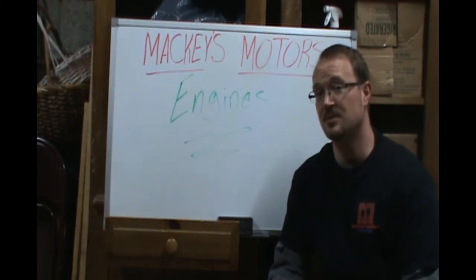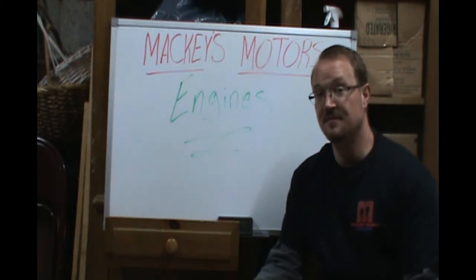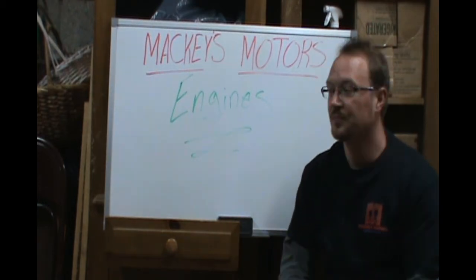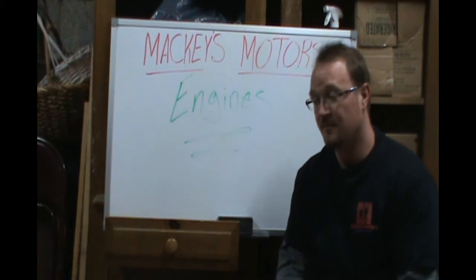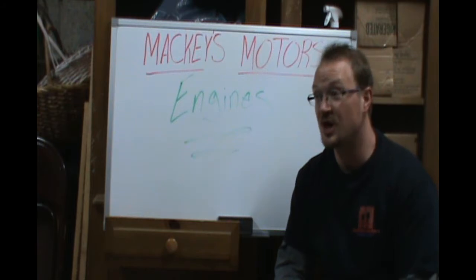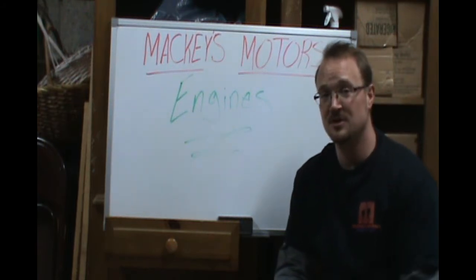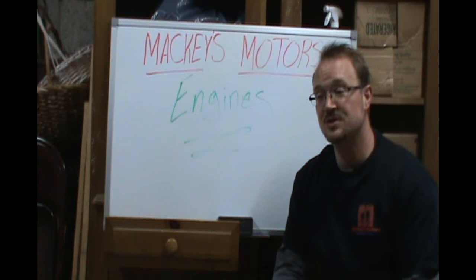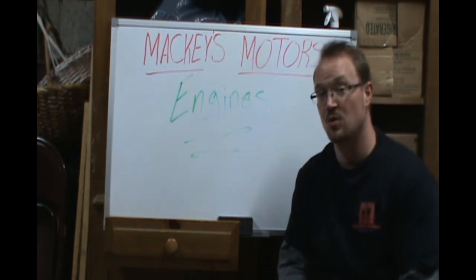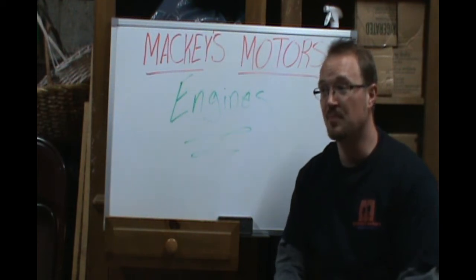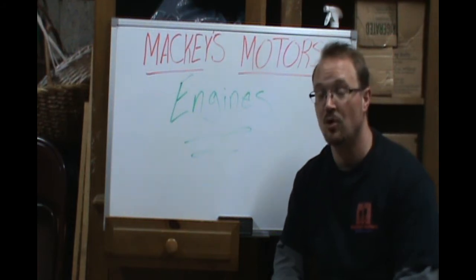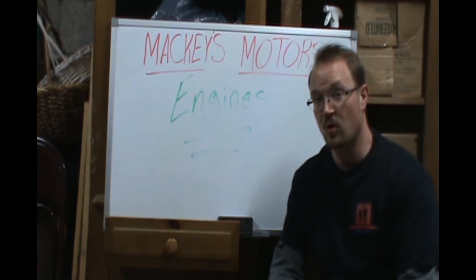As a mechanic, you have to be able to realize what mileage is on a vehicle and what it requires to be running at its optimal. Tune-ups can include anything from changing spark plugs to changing wires if a vehicle still has spark plug wires, to changing coils. It depends on the mileage and what manufacturers recommend. Always go by what the owner's manual says, because if there's ever an issue with warranty claims or with any type of manufacturer flaw or design defect, there could be TSBs or recalls that may pertain directly to what you're working on.